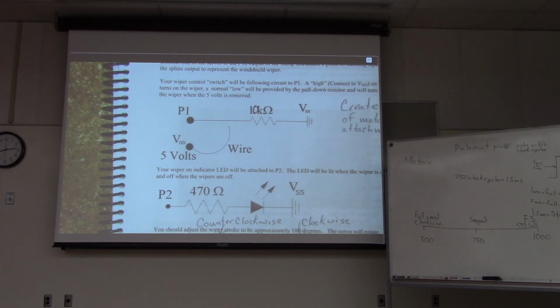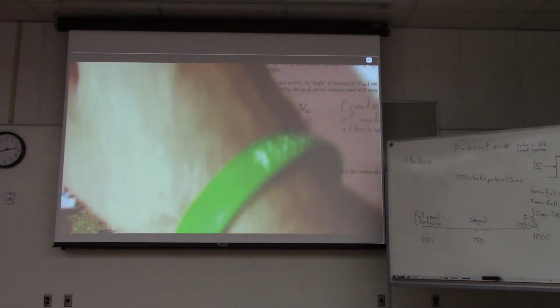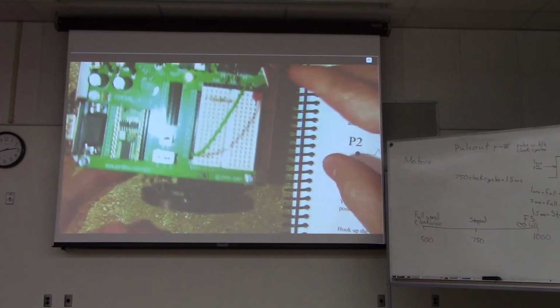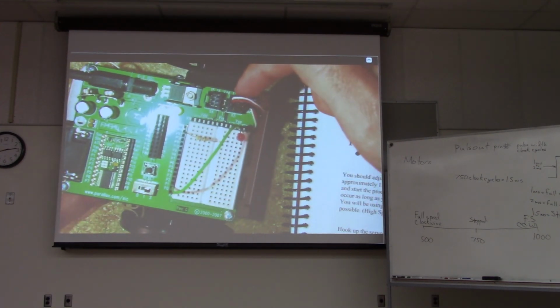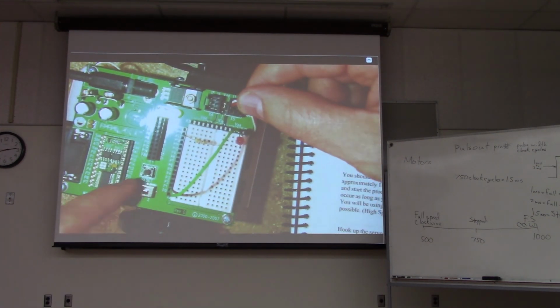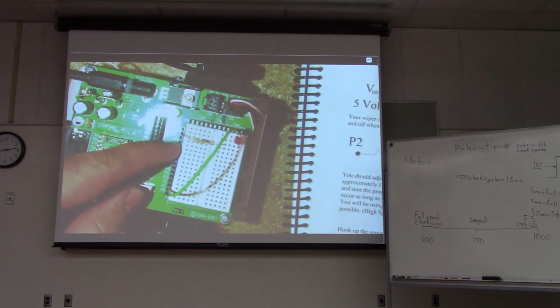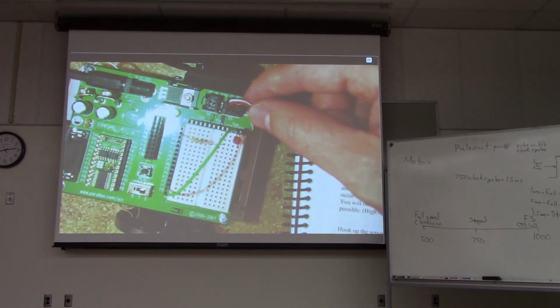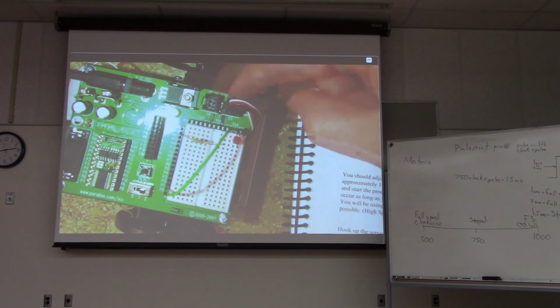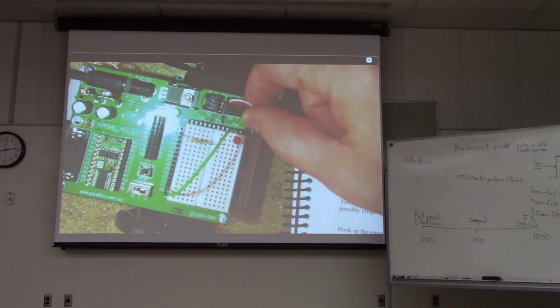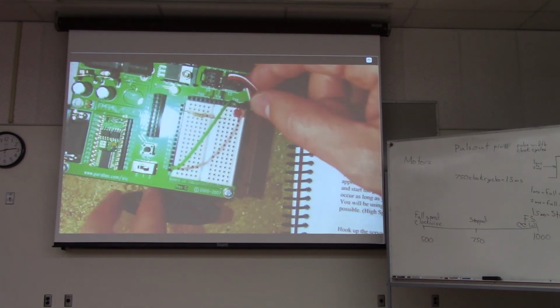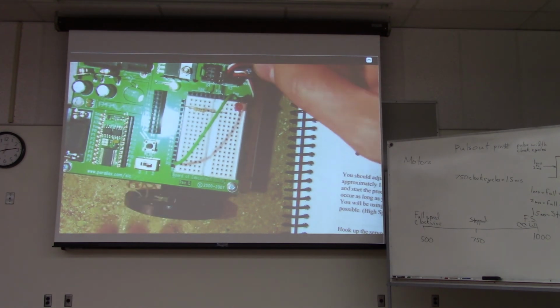So if you were to measure the voltage on the pin 12 that's up here at the top of the board, and then measure the voltage over here on the pin 12 over there, you would see the same thing. You would see pulses coming out of this pin 12 when you're sending them up here too. The reason that we have these sockets up here is because they are specifically designed for servo motors to be plugged in.